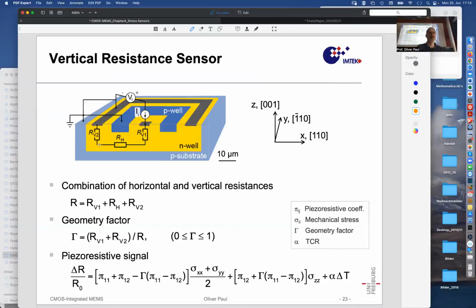Now, if you push, maybe there will also be in-plane stresses, because the material wants to expand and it can't. So by the Poisson's ratio, by the suppression of the perpendicular expansion, there may be also perpendicular stresses, which will also load onto that.